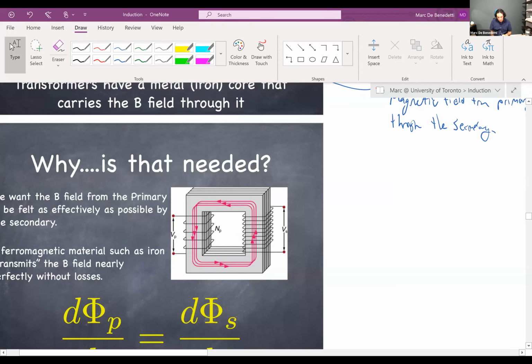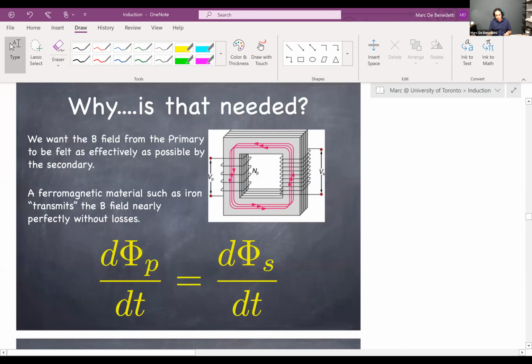So really what we've done here is we've turned that inequality. We knew that if the primary generated 10 field lines, then the field lines felt by the secondary is less than or equal to 10, right? You obviously can't feel more field lines than what's produced. So it's a physicist thinking in advance. We want to maximize the number of field lines that go through the secondary. How can we do that? We can do that by creating a pathway, a magnetic road for them to go through. And what we've done is we've changed that inequality into an equality.